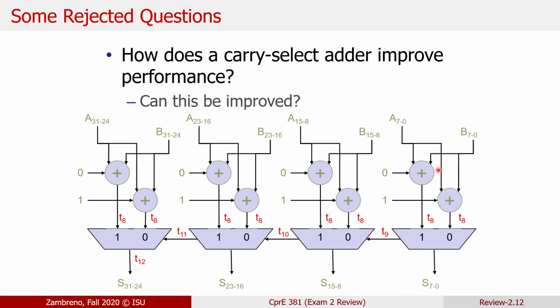So the carry select adder is recognizing that there is that ripple carry, there is that critical path, but ultimately that carry signal is either a 1 or a 0. Right? In terms of what it actually is at runtime, it's one of two values. You have two choices for what the carry signal itself can be. What the carry select adder is saying is, and maybe this second byte is the best one to look at, split up the adder in certain ways.